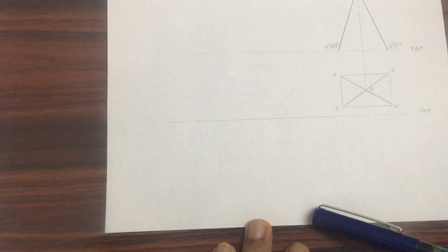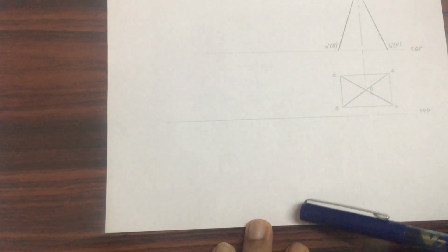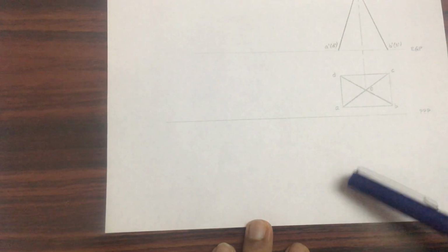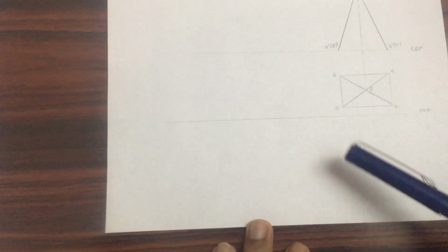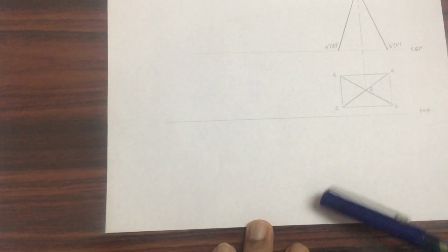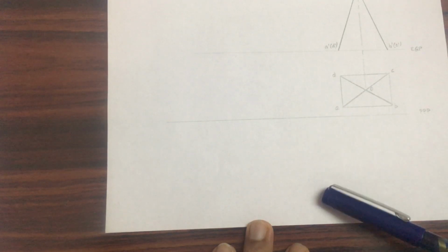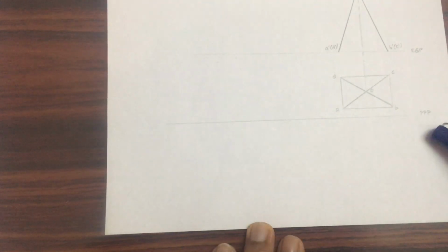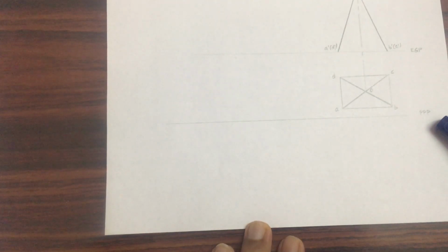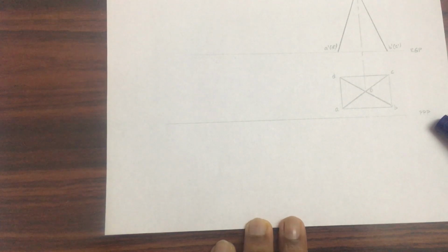If it was 70 mm, this distance should be something more than 7, maybe 8 or 8.5. As it is 30, I have taken a distance that is nearer to 30. In such a way you have to fit the drawing by taking the PPP line. So, firstly you have to draw the PPP line.